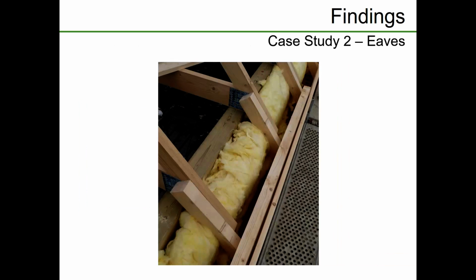This is case study 2, the mainstream one. This junction had no design. There was no detailed drawing for this junction, so the contractor basically had to make it up as they were going along. First thing, they've ordered trusses that are too short, or they were longer and they've cut them too short. So either way, there's a mistake being made there. They've extended the trusses then, to carry the fascia. You can see that that's a bit of an issue. So there was no drawing, then the contractors had to cobble things together.